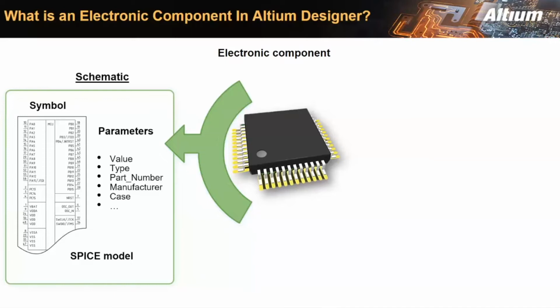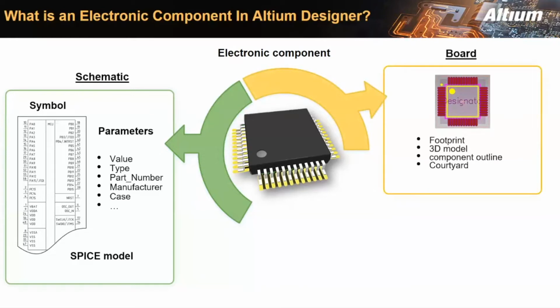During the simulation, the corresponding models will be used to model the behavior of the component for detailed analysis. Once the components are forwarded to the physical implementation domain, they will be represented as PCB footprints. The footprint may also contain additional graphics in mechanical layers, a 3D visual aspect, and more. Throughout all design stages, an important aspect of a component is availability and cost.